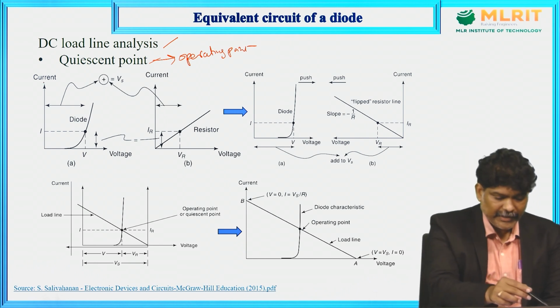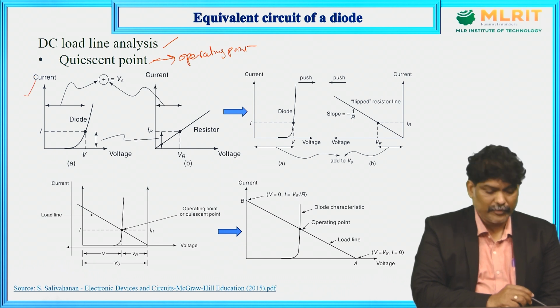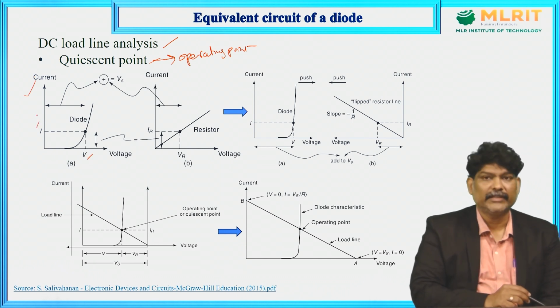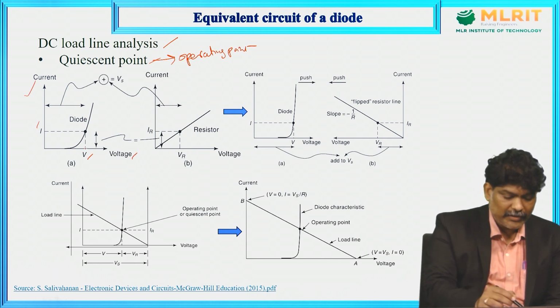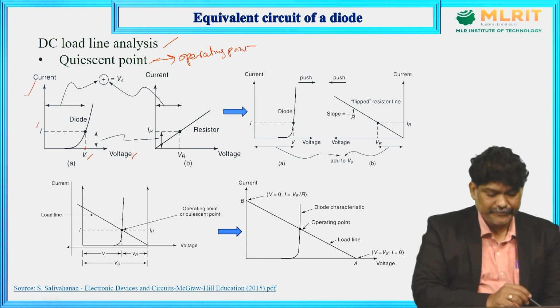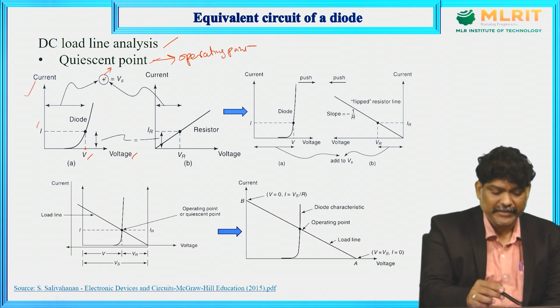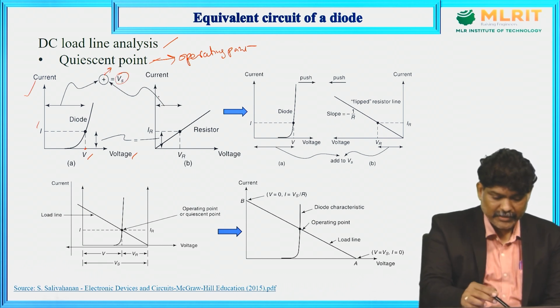See here, this is the VI characteristics of a normal PN junction diode. On the x-axis we take V, and on the y-axis we take I. This is the VI characteristics expression of a PN junction diode. This voltage is nothing but the cut-in voltage, we know. And this point, represented by a plus here, is Vs, that means the source voltage.